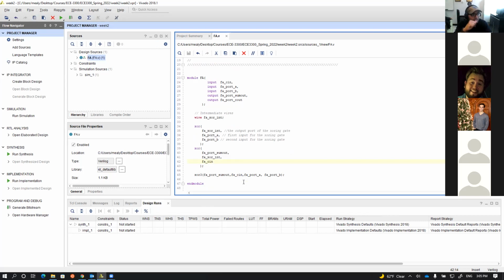Now, there is a redundancy here, right? Do you guys agree? Because I'm porting out here twice using two different techniques, this one or this one, right? So it's better for me to comment out one of them so I will not have a race condition. Because, don't forget, this tool is describing a circuit. That means it's also looking into the physics part of the circuit. Do you guys agree?